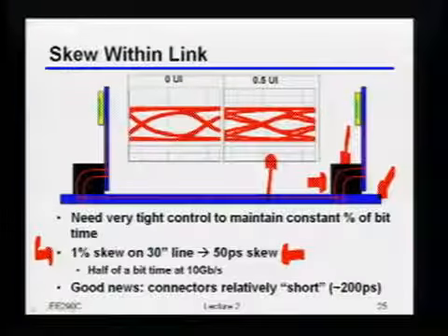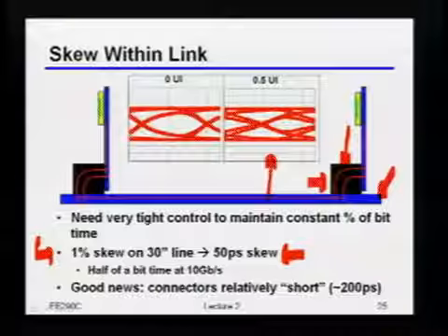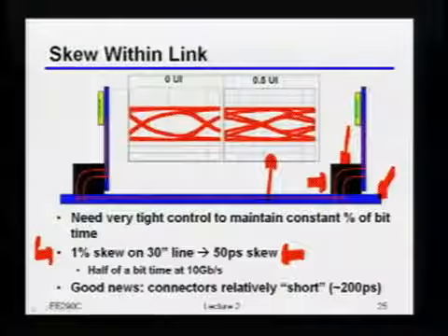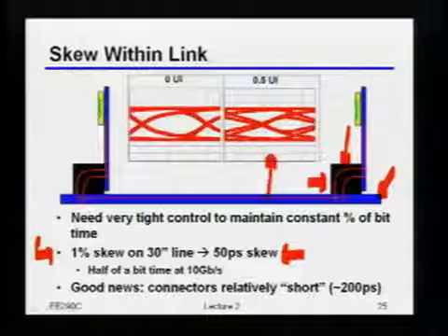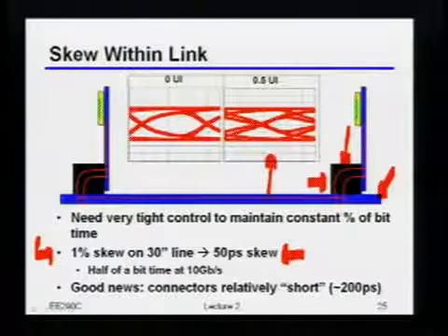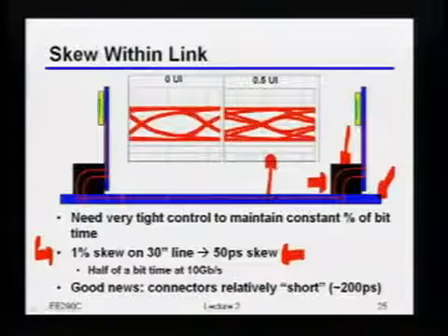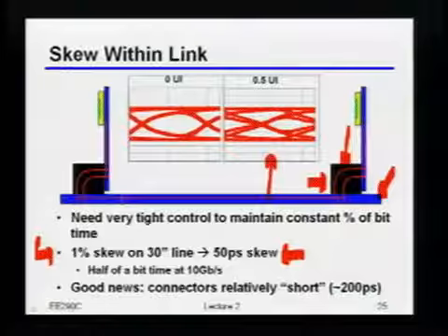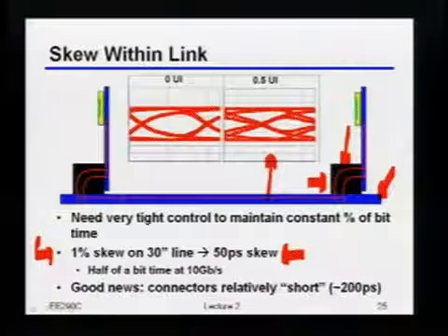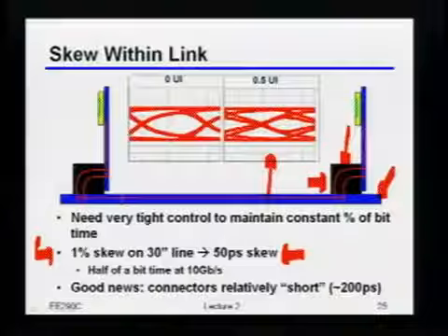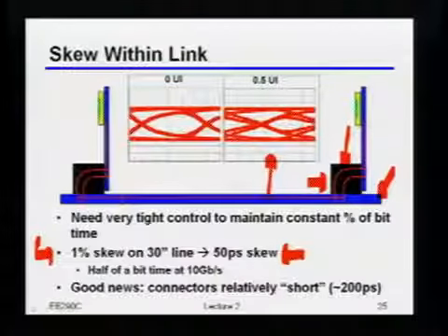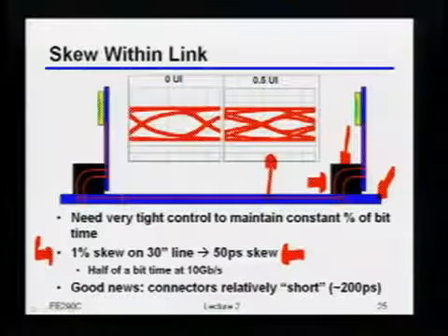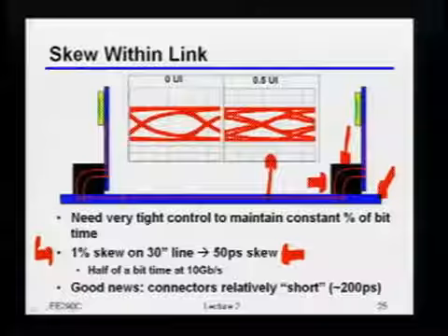It's a good question. Yeah? How do they control, I know the PCB dielectric constant tends to be all over the place. It is indeed all over the place. That's true. Now, remember, just like with, let's say, your IC layouts, if you're doing matching, you try and make things as closely matched as you can, right? So that hopefully if there is some global variation in the parameter, at least it's affecting both of the lines in the same way.